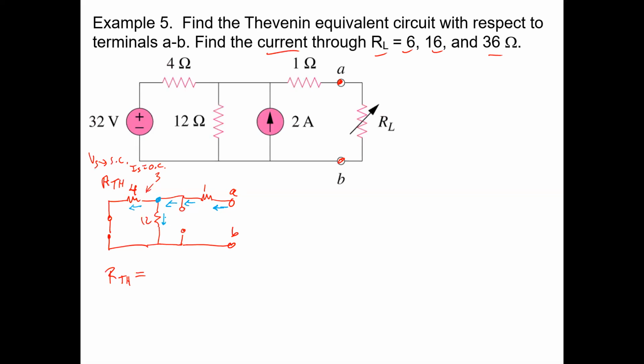So you have to find the parallel resistance of that. And then whichever way you go, you're going to meet up at this juncture, and everyone's going to go this way all the way to B. A lot of people look at the circuit from a different starting point, and you can get a different answer that way. It's always looking at it from A and B. So you should always imagine yourself driving from A to B and looking at what's in series and what's in parallel as you go along that pathway.